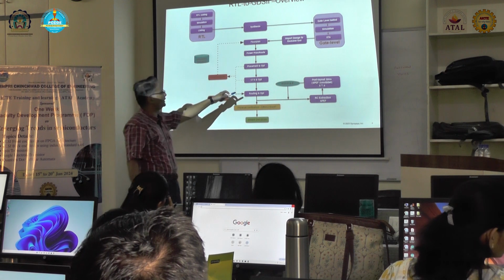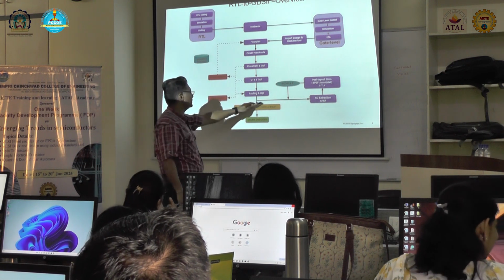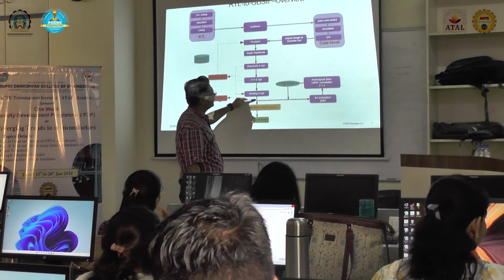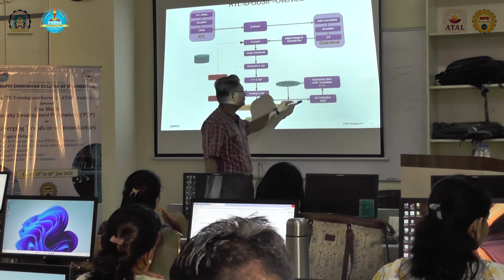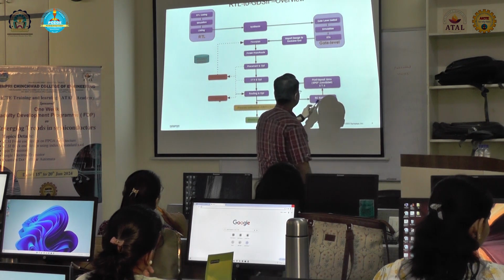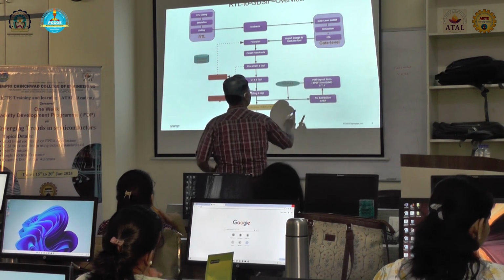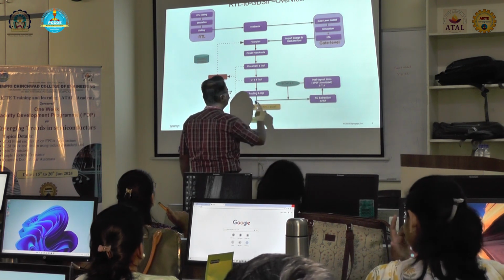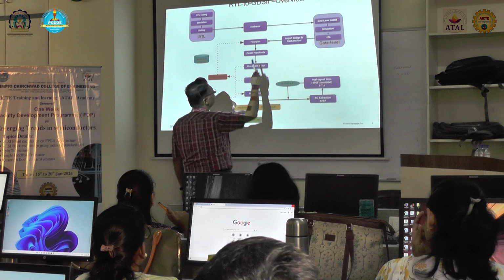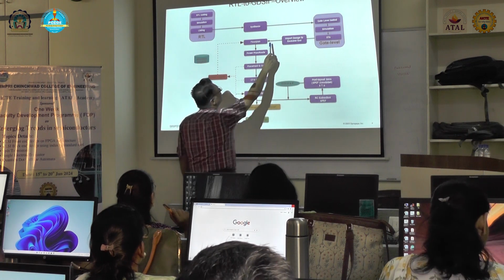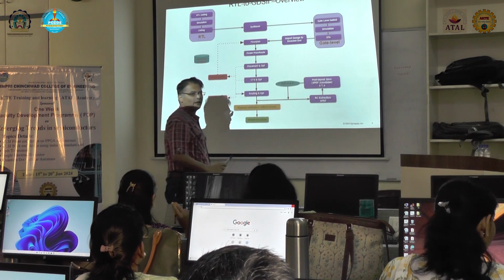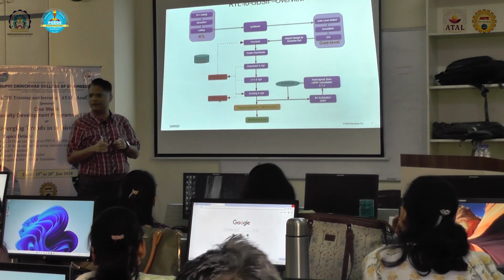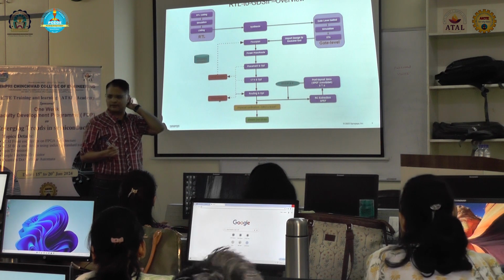Then comes, so here we have done the DRC, LVS. Now after we have done the routing, what we do is we take out the netlist again here. This netlist is the output netlist of backend. This netlist is the input netlist to backend. Right? We have two netlists. One is input to the backend stage, one is the output of the backend.